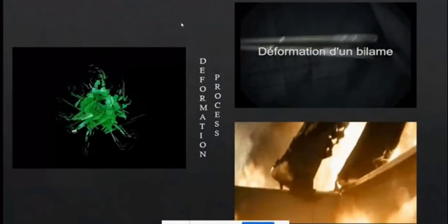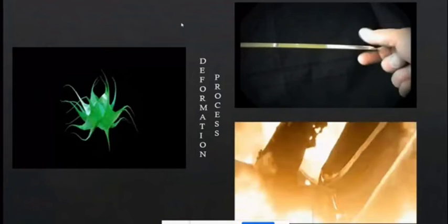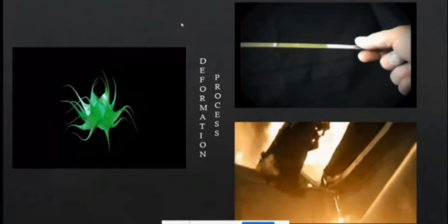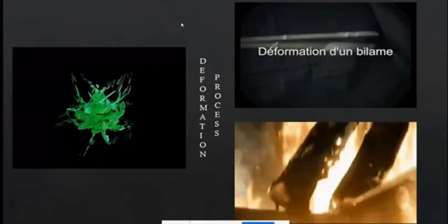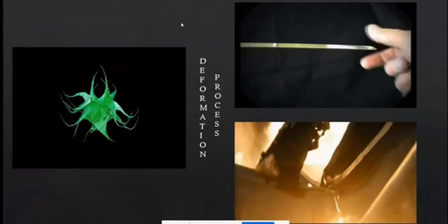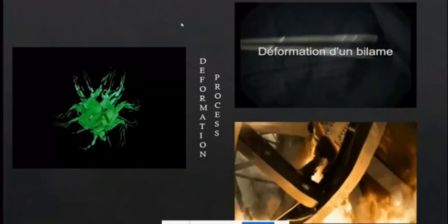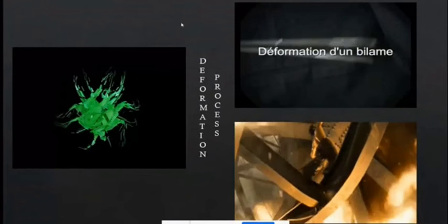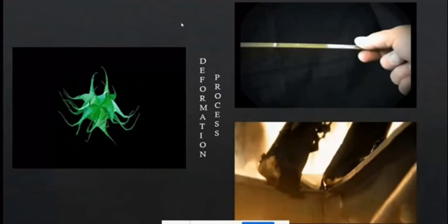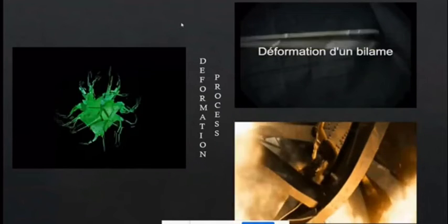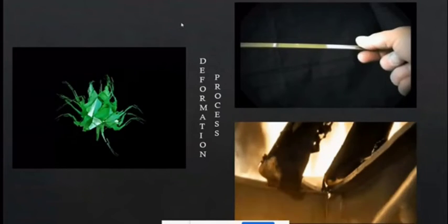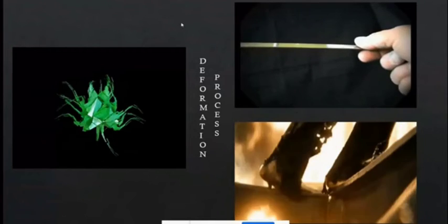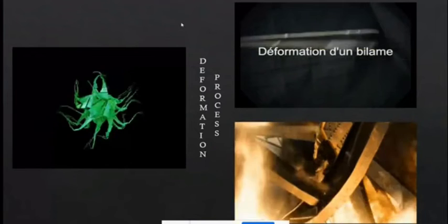A sequence of such processes is generally used to form material progressively from a simple geometry into a complex shape, whereby the tools represent the desired geometry and impart compressive or tensile stresses to the deforming material through the tool-material interface. As illustrated in figures, for the case of extrusion and deep drawing, deformation processes are frequently used in conjunction with other unit operations, such as casting, machining, grinding, and heat treating.